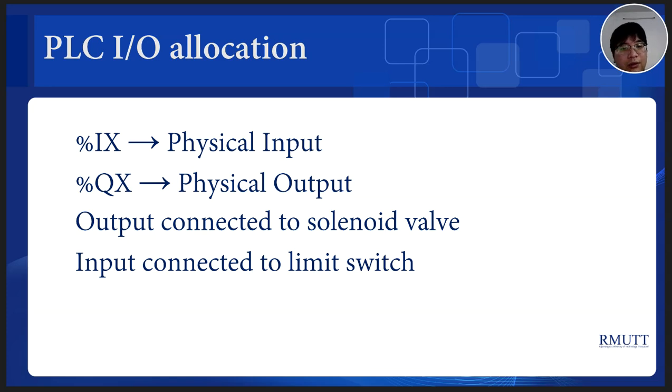This I/O allocation is very important because it connects the programming logic with the real hardware system. Without correct I/O assignment, the PLC cannot control the actual device properly.